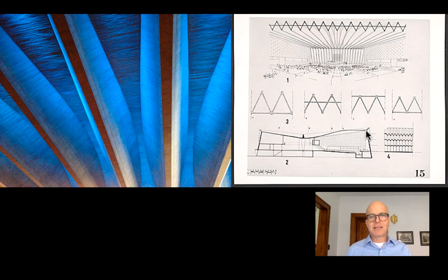That slab is a stiffening slab that allows the folded plate more capacity in compression. And therefore, as you go over the center of the span, it's going to be at the top. Continuous span, the compression is going to be at the bottom over the supports. You can see that that slab is tuned to run from the bottom of the folded plate all the way up to the top of the folded plate, where the bending moment is going to be at its greatest. Otherwise, though, this is a fairly simple scenario.